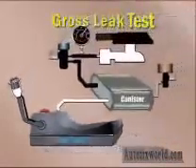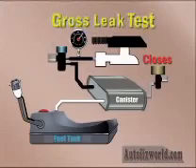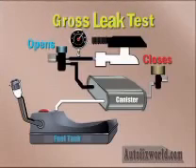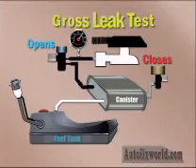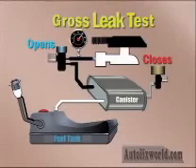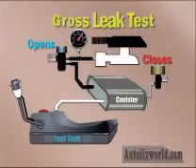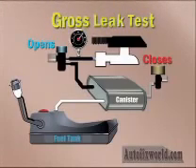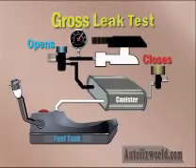To test the system for leaks, the computer first closes the vent valve to seal the system. Then it opens the purge valve, applying engine vacuum to the EVAP system. If the pressure sensor detects sufficient vacuum, the gross leak test passes. If no vacuum develops because of a large leak in the evaporative system, a gross leak DTC is stored. This is the code that turns on the MIL in some vehicles when the gas cap is left dangling on the quarter panel from its tether. Gas fill caps have been modified in recent model years to make them easier to tighten. Early OBD2 vehicles with hard-to-tighten gas caps stored many EVAP codes for gross leaks.